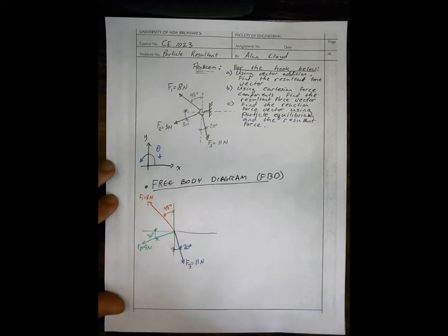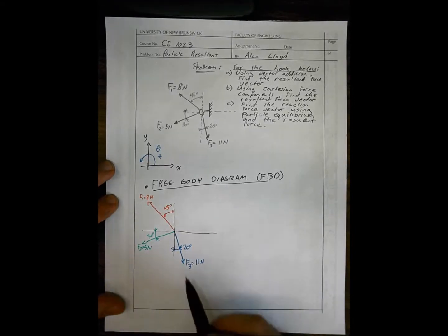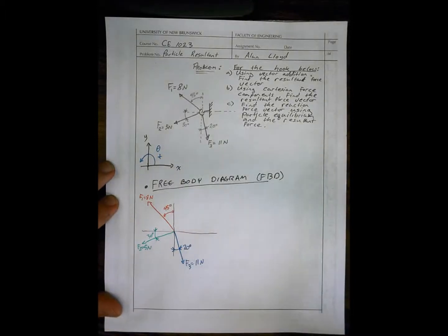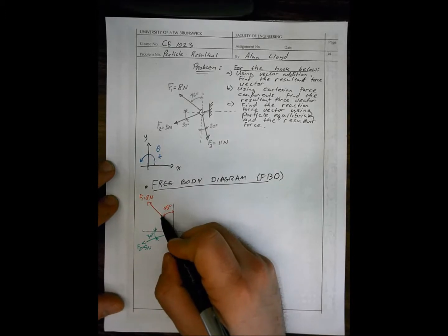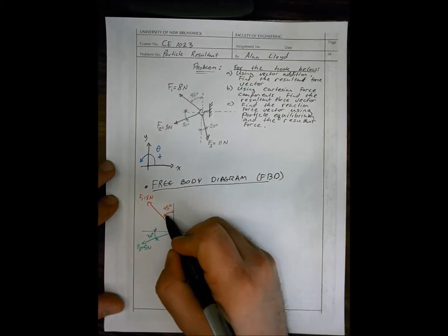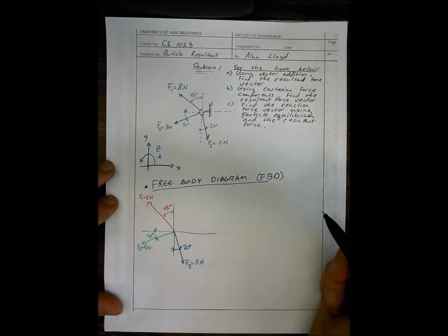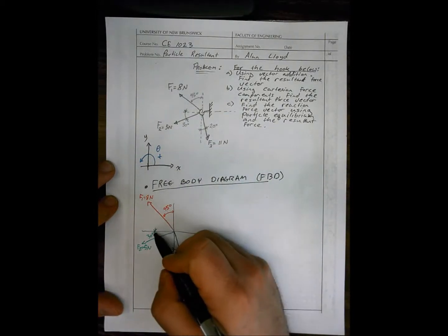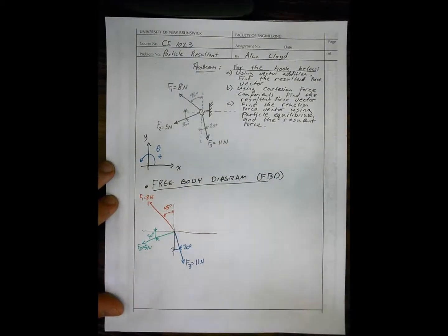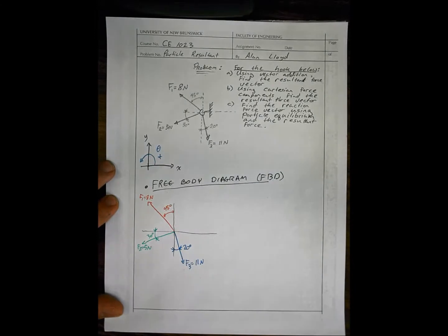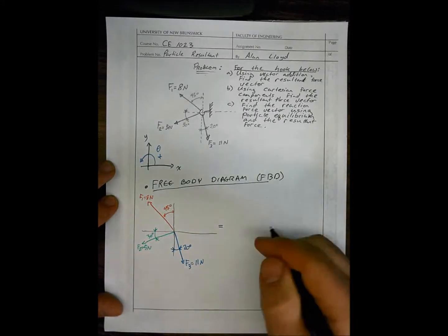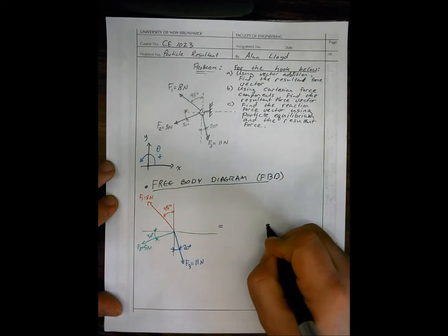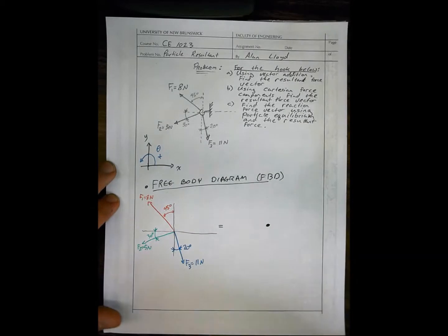Now you'll notice that none of these angles are defined in terms of our theta as positive acting off of the x-axis. So if we want to get the real theta for force 1, we need to add 90 degrees to that. The real theta for force 2, we have to add 180 degrees, and we have to add 270 degrees for theta 3. And we'll do that in a little bit. For now, let's break this down into what we would consider our Cartesian force free body diagram.